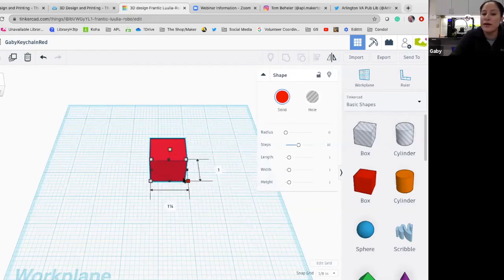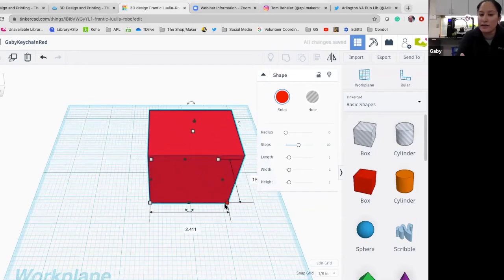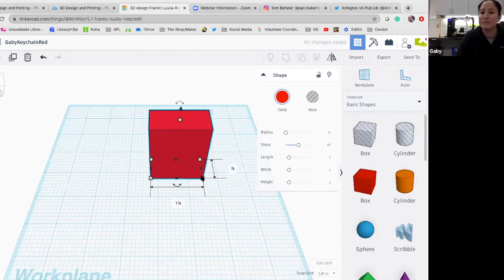But if we do want to keep this a square, or let's say you've put together different shapes and you want to make sure that you're scaling it up in size and not just dragging certain sides and distorting the figure, you can always hold down the shift key on your keyboard and click on that corner again. This time it should keep everything in proportion, and you'll notice that the cube is now increasing in size, but you're not dragging certain sides of it. That's actually a really important tip to keep throughout your modeling.